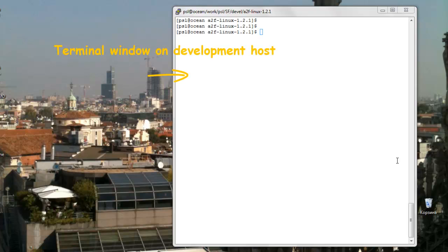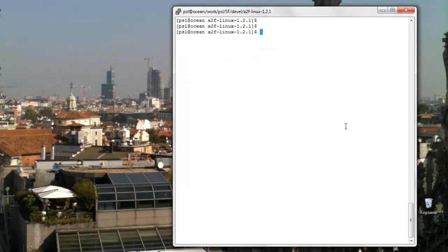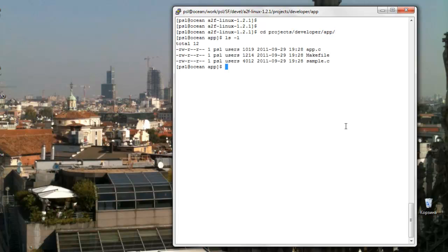The Linux SmartFusion distribution provides a sample project called Developer that is intended as a template project that can be used to jumpstart development of custom user space applications and loadable kernel modules. From the kernel configuration startup sequence perspective, Developer is all ready for NFS mount. From the BusyBox configuration perspective, Developer enables the insmod, lsmod, rmmod commands in a multi-call BusyBox binary to allow management